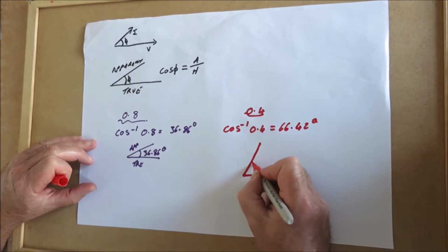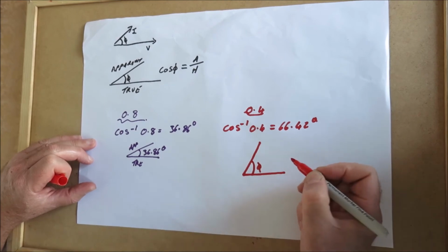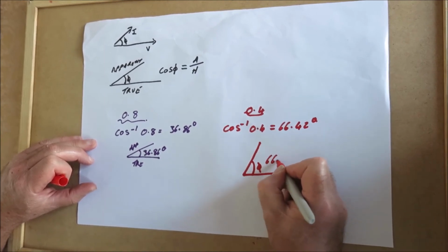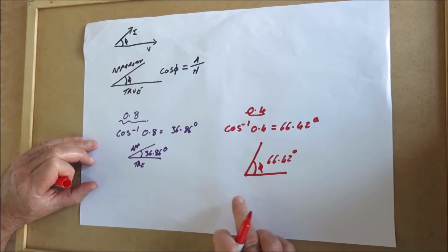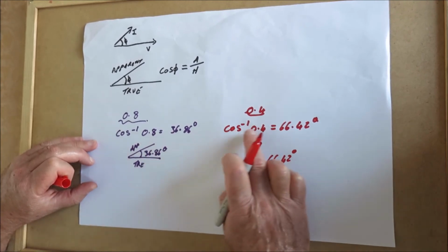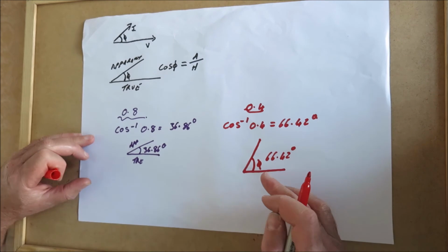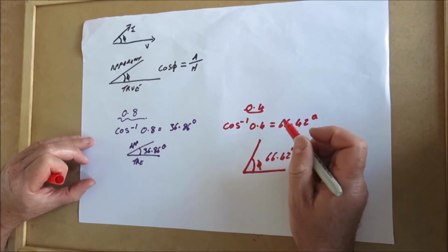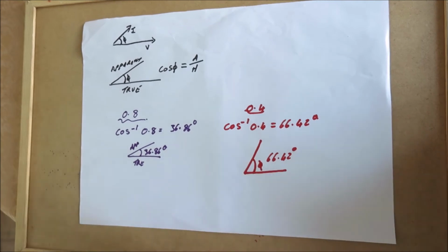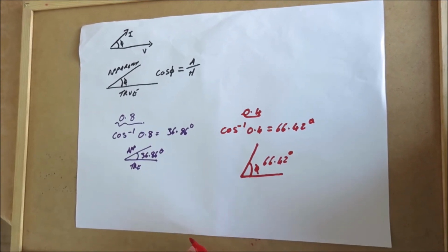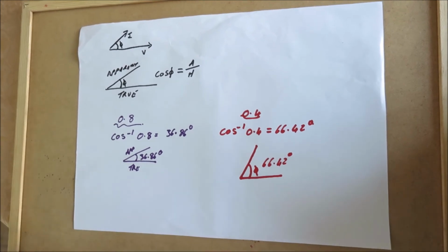So we've now got a larger angle between them. It's not quite to scale obviously, but that phi angle there now is 66.42 degrees. So as the power factor gets worse, we can see the angle there getting worse, and consequently the reactive power will get worse as well. So we need to put in power factor correction capacitors to correct that.